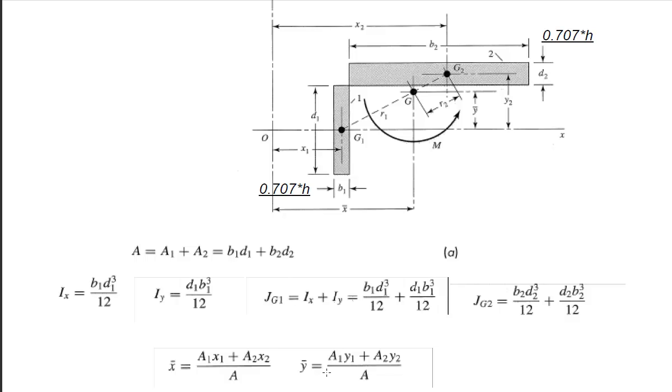Now, interestingly enough, in this shear loading we're going to be doing a force over area calculation, but we're also going to be doing a TR over J calculation. And so we're going to need to calculate the J value, and that can be done in an incremental process. Each rectangular weld segment has a moment of inertia about a particular axis, and since they're rectangles, that can be computed as BH cubed over 12. We just have to be careful which one we're cubing.